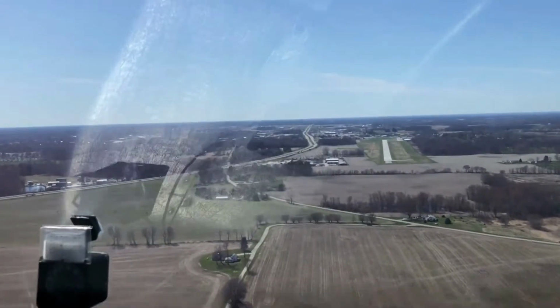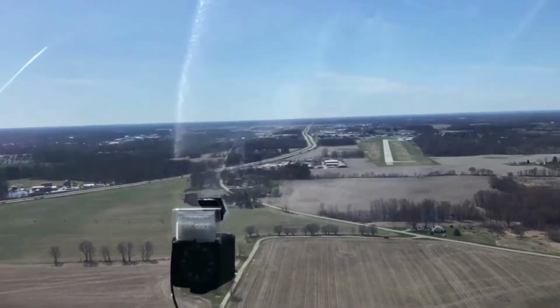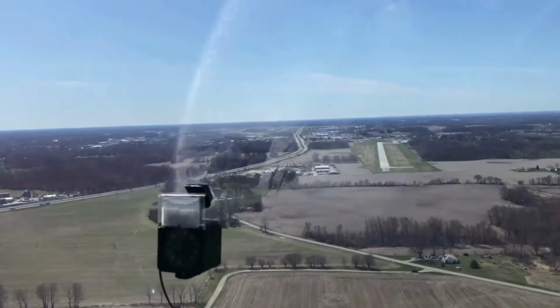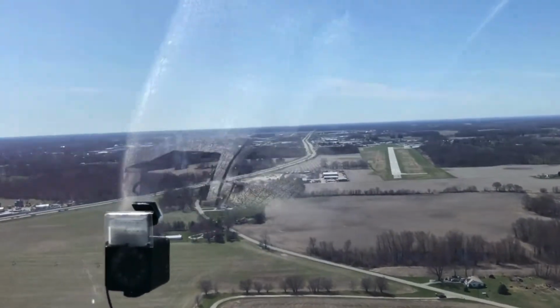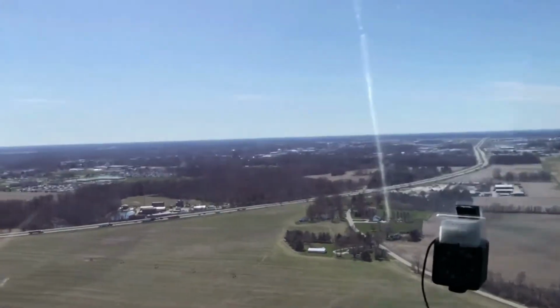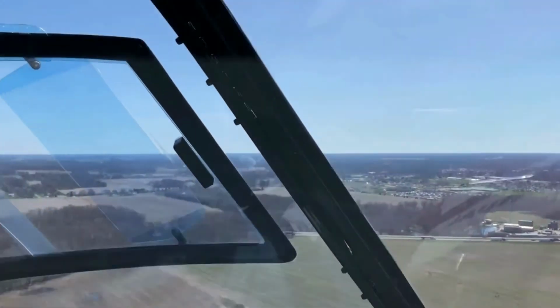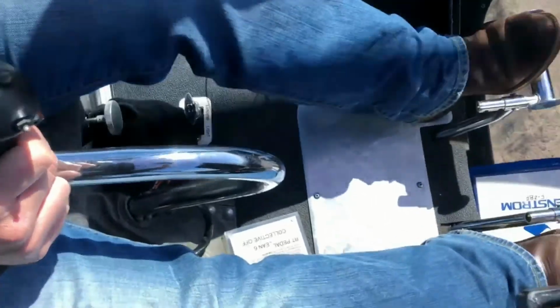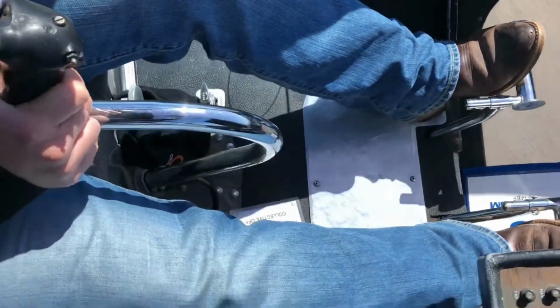So we're flying along, Gary's getting ready. We have 500 feet HEL. He has about 75 on his airspeed, which is good. We can enter a little bit higher than the glide speed that we want. So he's getting prepared, and when he enters, he's going to lower the collective, hold off a little bit of throttle. He's going to pull just a little bit of aft cyclic, and he's going to add some right pedal. We do this every time.